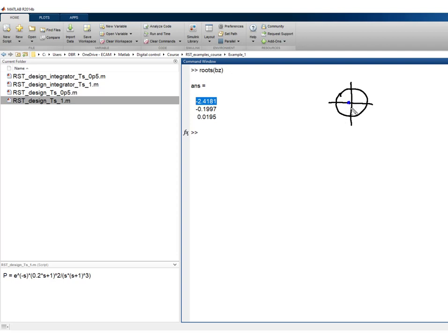This kind of root is kind of limiting because it's close to the origin, right? You could put it in B plus because its influence is going to disappear rather fast. Here we have decided to put it in B minus because if you compensate it, you'll have it in the denominator and this will cause this oscillating behavior.